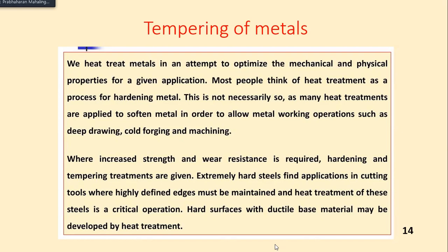Many heat treatments are applied to soften metal in order to allow metal working operations such as deep drawing, cold forging, and machining. These are the operations where increased strength and wear resistance are required. Wear means removal of a certain amount of metal at the time of working, very little amount, less than 0.001% level. That is where wear resistance is required. Hardening and tempering